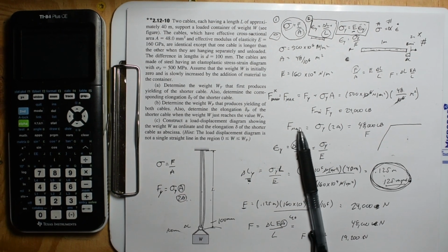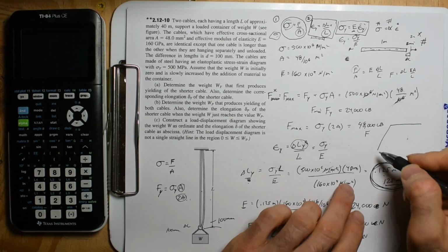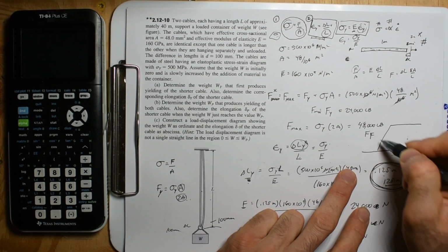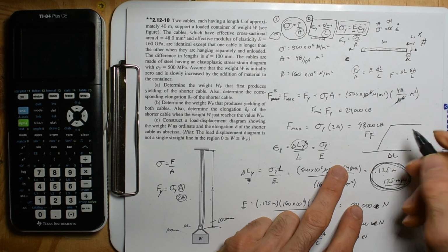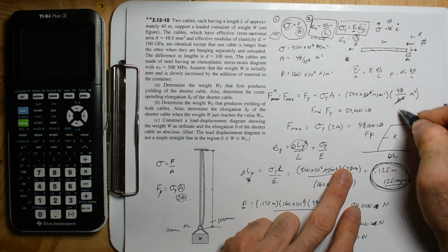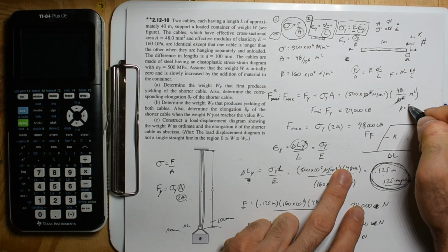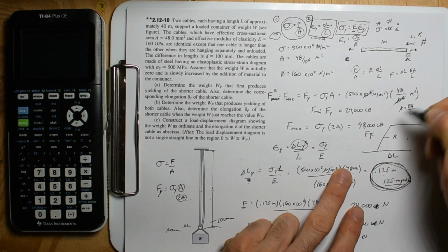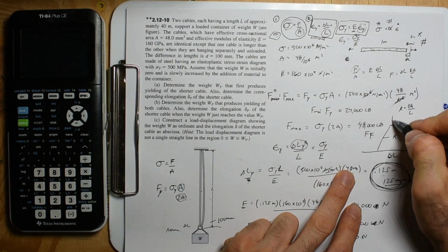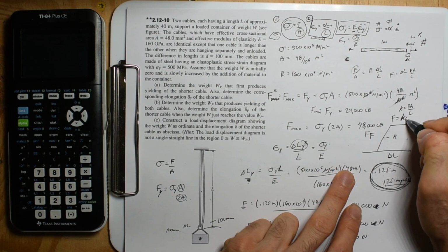All right, we got to wrap it up. But whether you say this graph is force times change in length, which then your slope is k, and then your k is EA over L, you should be able to spit that one out because the force of a spring is k change in length.